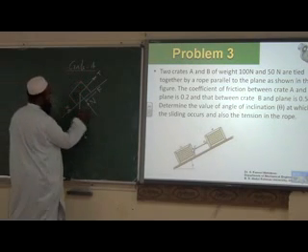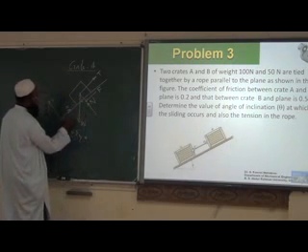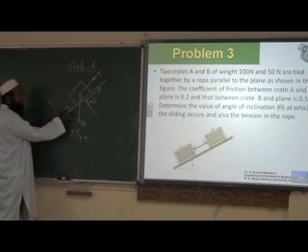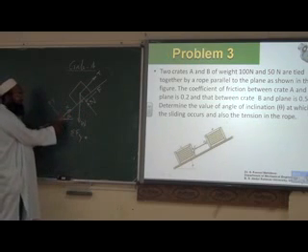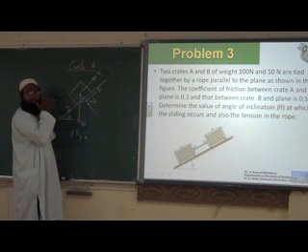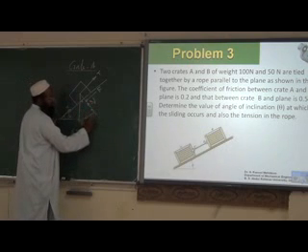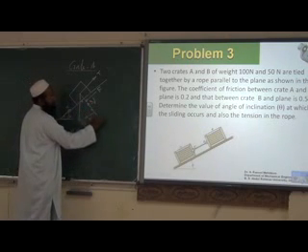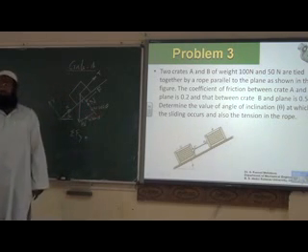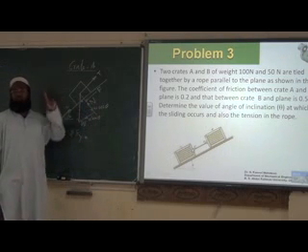Sigma Fy. So the angle we don't know. At present, this is theta. The angle made by the inclined surface and horizontal is theta, so the angle made by the normal and W will also be theta. So this will be W sin theta, and this is W cos theta. W is resolved into these two components.